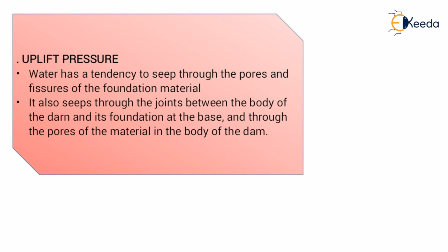Hence, net foundation reaction due to vertical force will reduce. According to the USBR recommendation, the USBR suggests adoption of uplift pressure intensities equal to the hydrostatic pressure of water at the toe and heel, joined by a straight line in between.